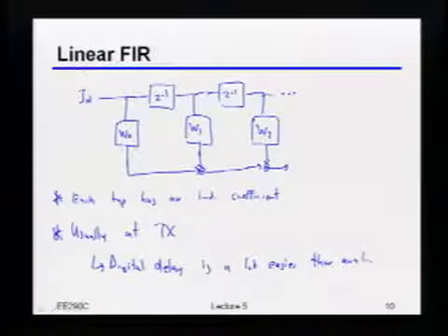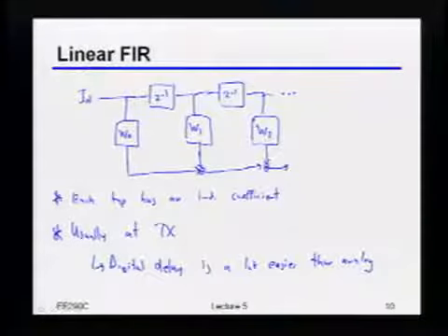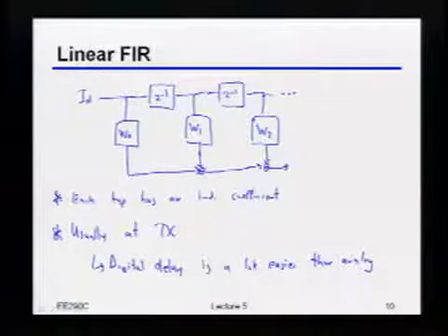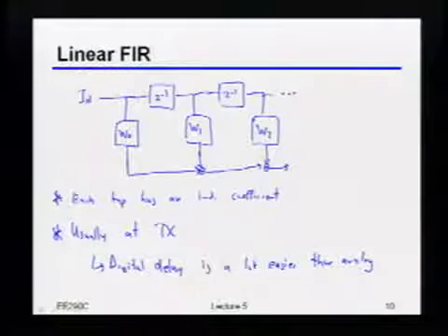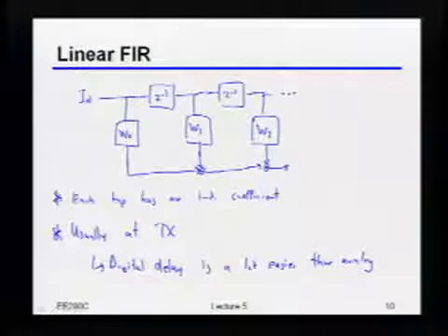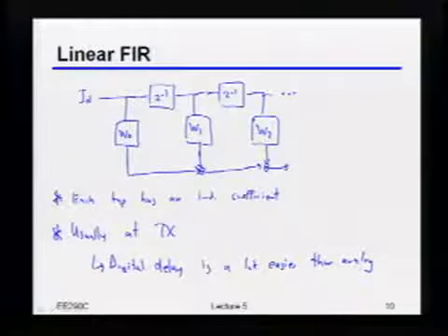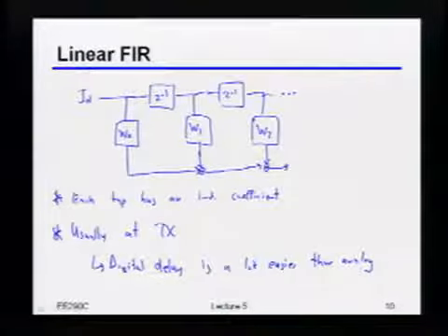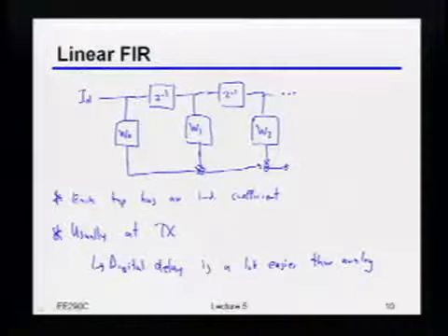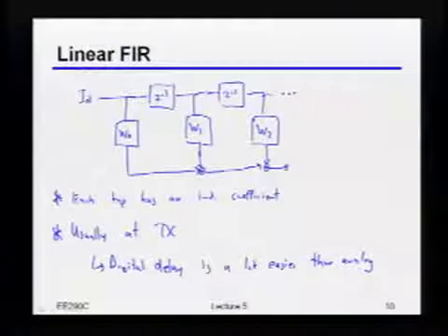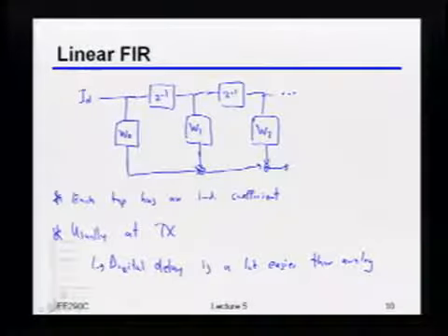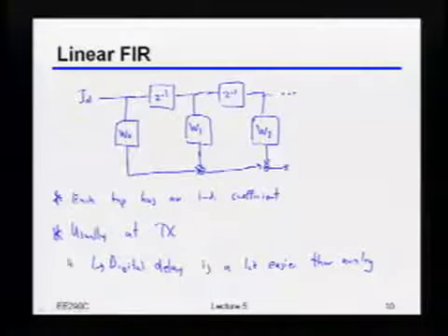If you build delays with digital gates, you can do that without noise. If you do it with analog, it's kind of a pain. So, Igor is right. It does actually save you an ADC. Although, by the way, you could build this on the receiver with an analog circuit too. It's just, if you do it with an analog circuit, then you can't use the digital delay. And then you do need an ADC, and there are some other issues with that. Again, we'll talk some more about the real circuit stuff. For this lecture, I mostly want to focus on the high level trade-offs. But it really is that digital delays are nicer than analog delays, which is why you tend to put this at the transmitter.